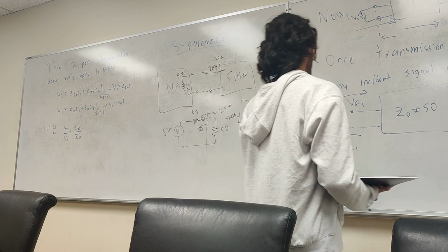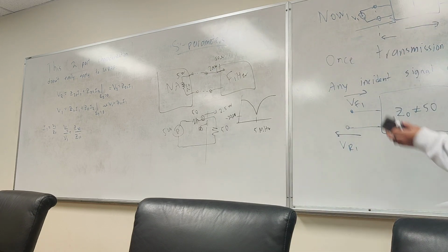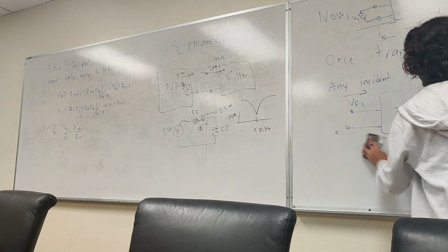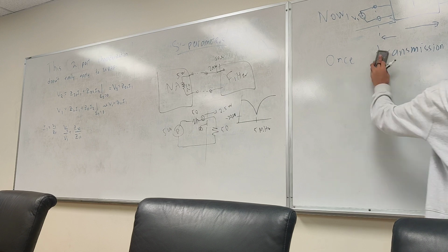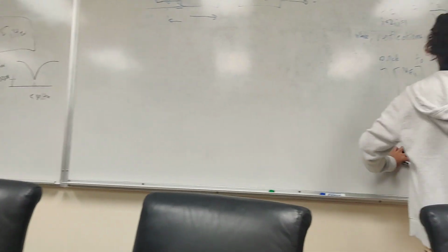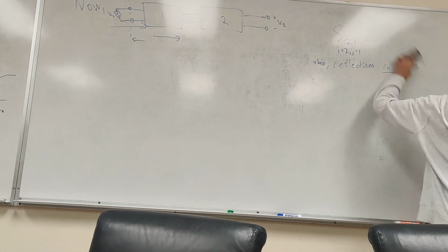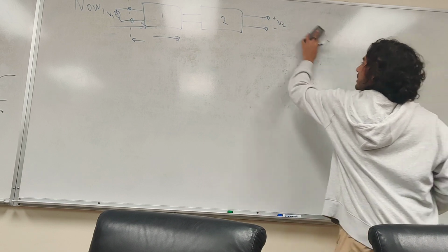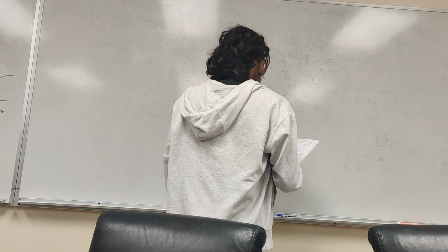Transistors, we can think about as a 2-port. 3 terminals, but you can just make your emitter ground, and that way I'll draw it up. But what we're going to do is say transistors are a 2-port themselves, right? And that's kind of what we did before, the small signal model. We made a 2-port. So let's do that.